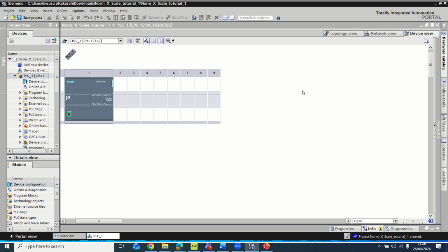And the reason for this is, there are certain devices that give analog data. For example, temperature control, tank level measurement, pressure measurement, flow measurement, and motor speed feedback. All of these give an analog signal. And how can a PLC convert this into discrete information which we can read? For example, temperature in degrees Celsius. How can we read that? Or maybe tank level in meters.